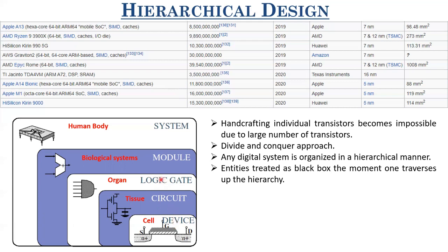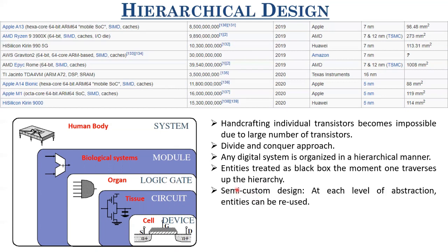So for a logic gate designer, a circuit is kind of a black box. For a module designer or an architect, this logic gate is kind of a black box. So it goes like that. Now, from full custom design, which is handcrafting individual transistors, we have come to a level where we are not exactly fully handcrafting the chip. What we are doing is something called semi-custom design.